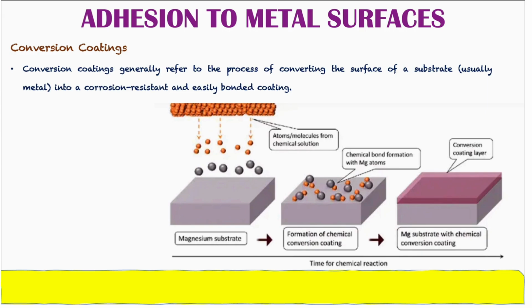And of course, there is also another type of coating which is called the organic conversion coatings. The organic conversion coatings involve chemical interactions of resin molecules. These molecules undergo processes like condensation and polymerization, which can be addition polymerization or oxidative polymerization, due to which a cross-linked network is formed.